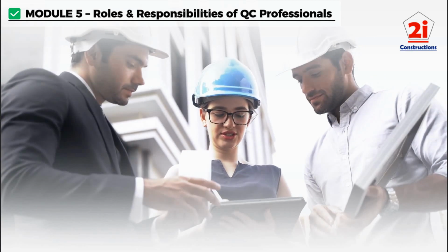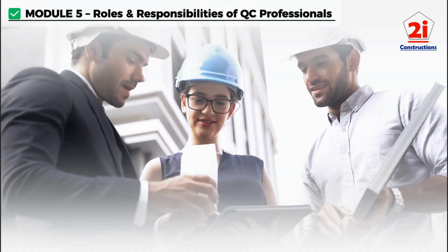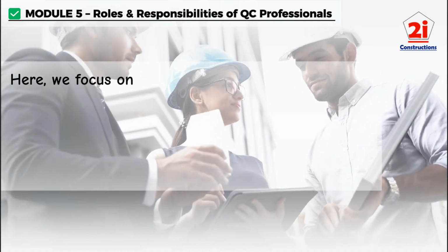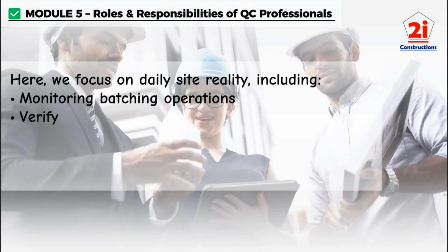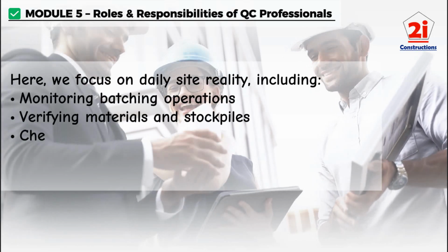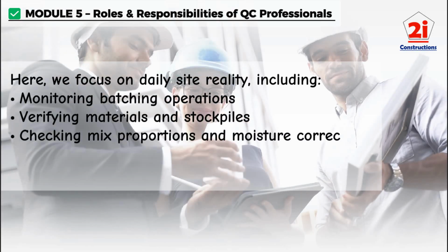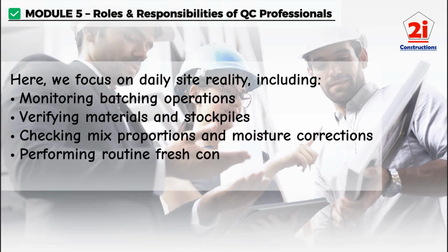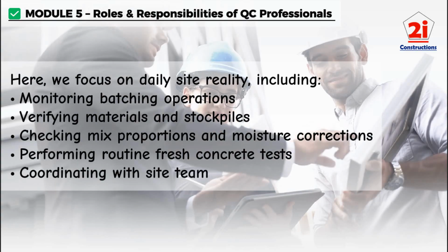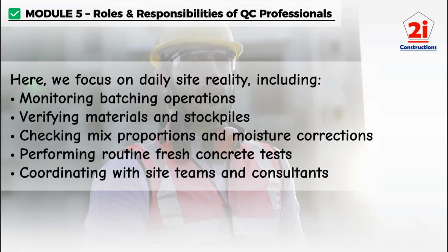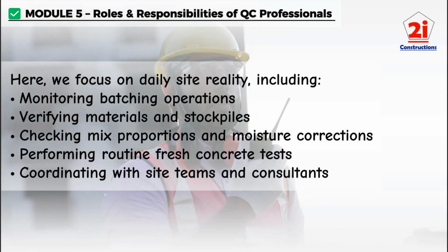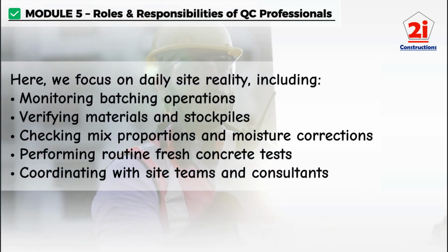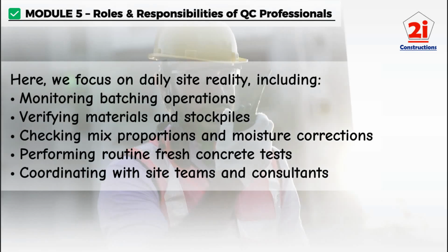Module 5, Roles and Responsibilities of a QC Professional. Here, we focus on daily site reality, including monitoring batching operations, verifying materials and stockpiles, checking mix proportions and moisture corrections, performing routine fresh concrete tests, coordinating with site teams and consultants. This module defines what a QC professional does every single day.